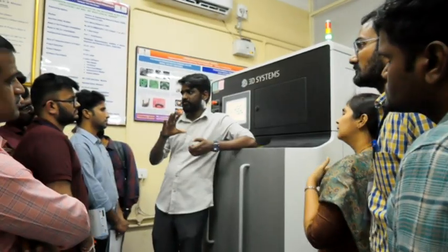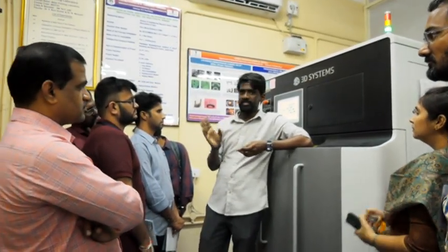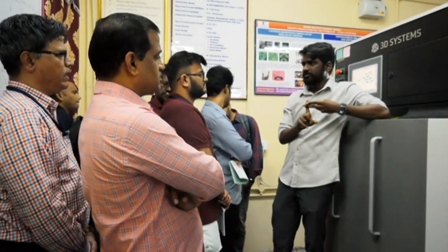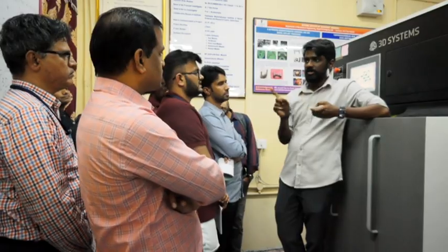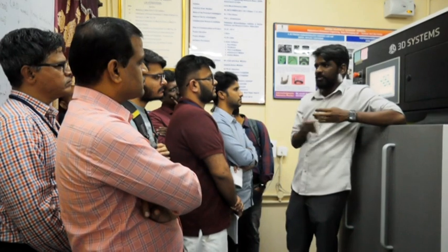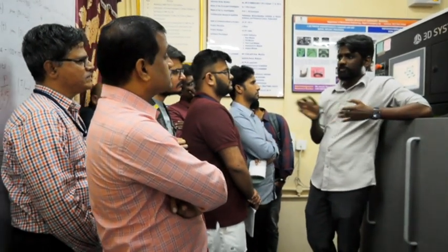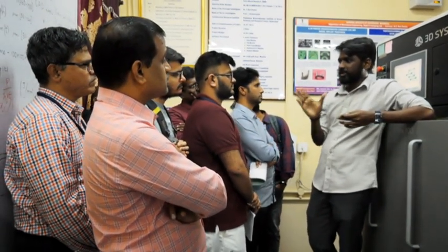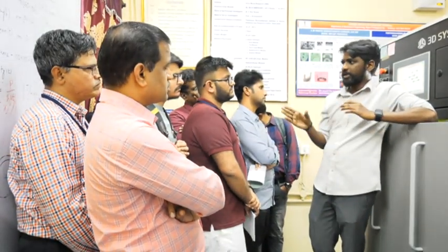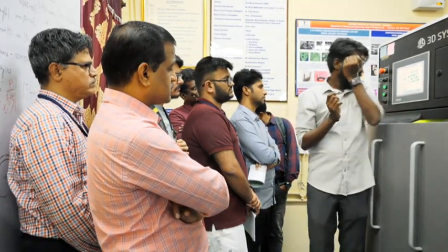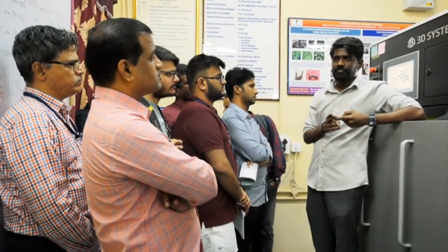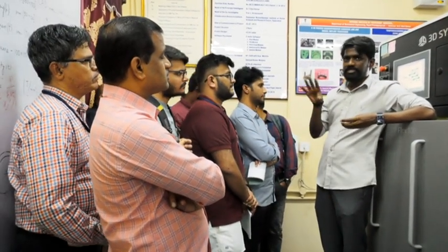Thereby, you have to do the design using some process parameters like hatch spacing, scan quality, layer thickness followed by laser power. Right now we can't change the layer thickness here; we are following the same default, because it depends on the powder quantity. We have to take care of the powder particle size also. In the medium size, we have to follow 30 microns thickness, followed by scan speed and scan strategy. Those things we can directly change in the 3D Expert software.